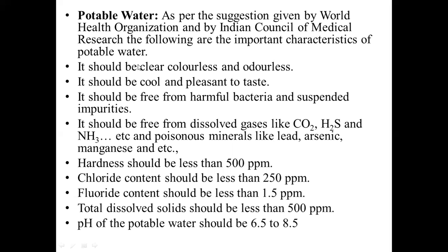Now we have talked about what is meant by potable water. Potable water is the water with the characteristics or specifications needed for drinking purposes, and these specifications are given by WHO and by the Indian Council of Medical Research. Now, these are the specifications. It should be clear, colorless and odorless. It should be clean and pleasant to taste. It should be cool, and it should be free from harmful bacteria and suspended impurities. It should be free from dissolved gases like CO2, H2S, NH3, etc., and poisonous minerals like lead, arsenic, manganese, etc.